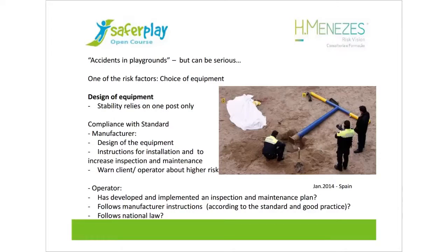For instance, in this case, it was an accident in Spain with the equipment complying with the standard, with certification, with certificates, and what happened probably had to do with a bad installation and then lack of inspection and maintenance. But at the design stage, when you choose a one post equipment, which is an equipment that relies on one post only for stability, we know that we are offering something where we will need more attention, more inspection, more maintenance.